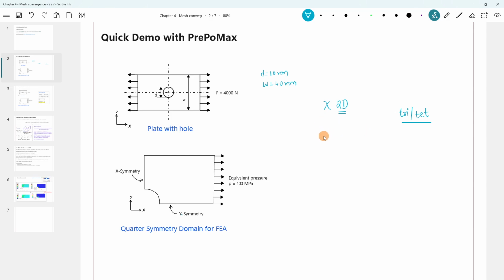The solver does not allow 2D elements. If we model a first order tria element, internally it expands into a 3D element. This tria will become a wedge element, not a tet element. This is the reason we will not be doing a 2D analysis. So we will take a 3D model, mesh with tet elements and understand the FEA workflow.